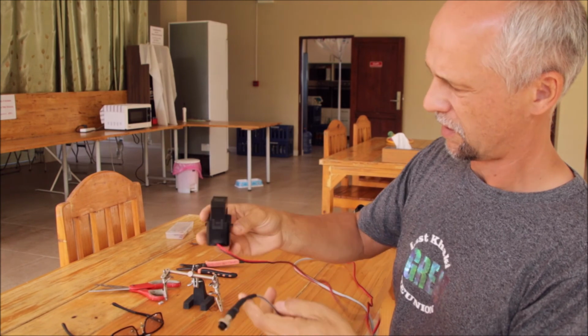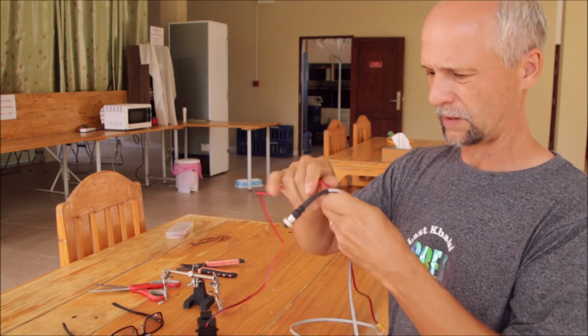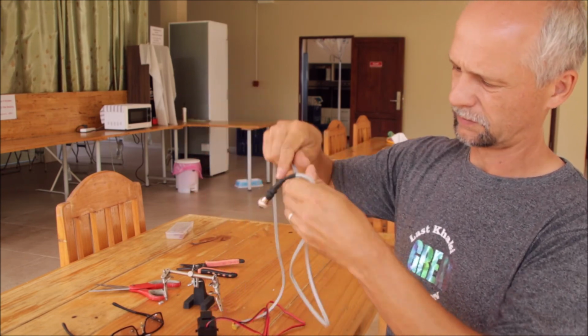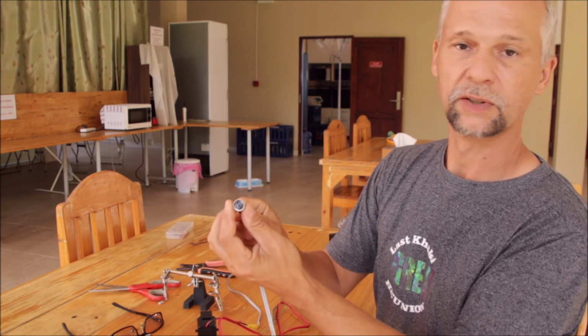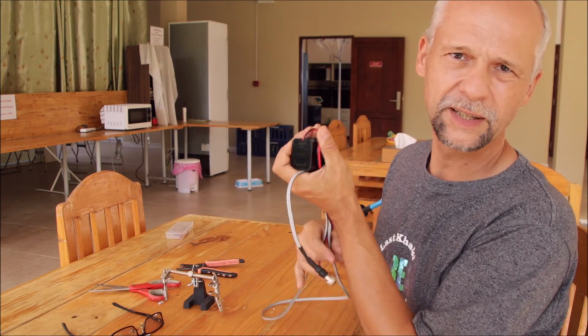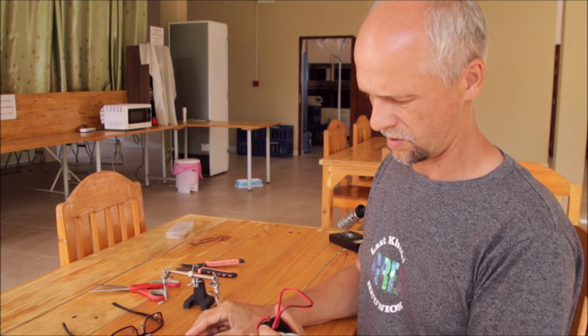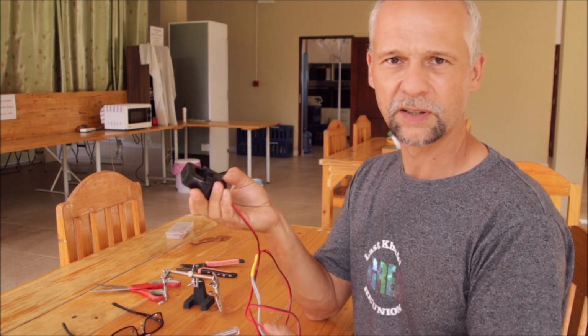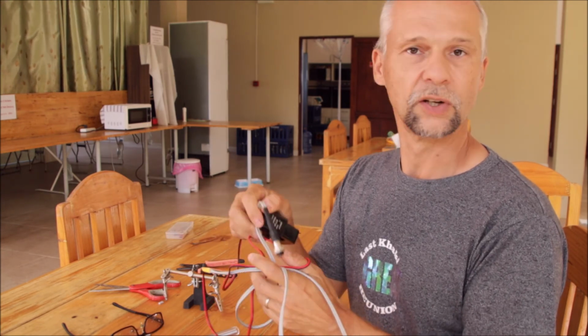So that was it. Fast and easy job. We have our new CT, cable connection number 1 and the GX12 2-pin connector on the other side. So we are ready to go to the Powerwall again and disconnect the old CT, and then we will put this one into the main distribution board on the cable which I showed you before, and just plug in the new CT to the inverter, and then everything should work as before.